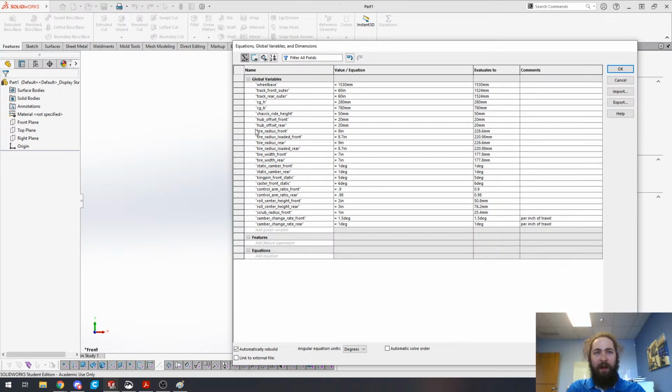And I guess for your tires, that's not really so much about reason as it is about what tires you have, but generally speaking, you try to figure out what a good wheelbase is, what a good track width is, figure out where your CG is going to be, and try to design that and mold the design of that towards kind of what your design specification is.